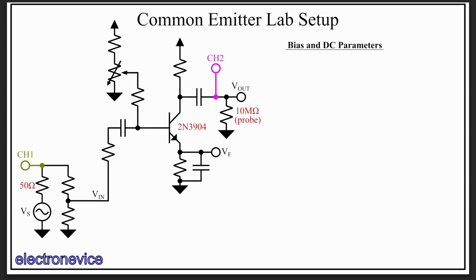We will also need to see that input voltage on the scope while measuring the output voltage, but the oscilloscope will have a hard time measuring such a small signal directly, so we'll measure the function generator output, and that will be our proxy for the input voltage. The divider ratio we'll use is an attenuation factor of about 101, because that's easy to make with a 10K resistor and a 100 ohm resistor.